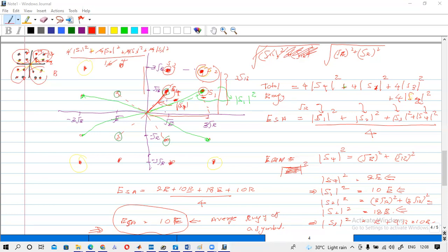Those energies are based on the voltage values and the bit duration. The energies depend on those 2 parameters. So there is no point in equating QAM energy with PSK energy in a practical system.